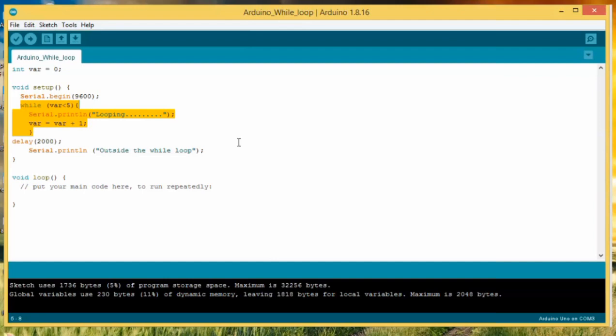The receiver will receive all the bytes together before you can know what kind of information was sent. So in this case, you use the while loop, where you say that while the data is available, make sure that you receive all the bytes that come in with that data, to the last byte. So this is how you can simply make use of the while loop.